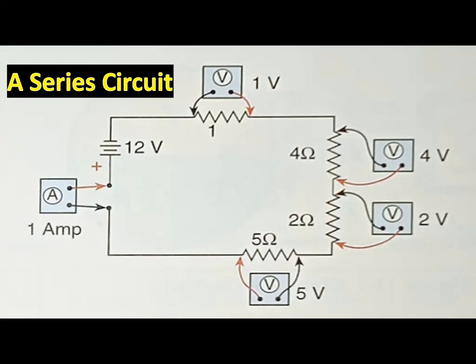The heater blower circuit is an example of a series circuit. The resistors in the blower circuit that control blower speed are switched in series with the blower motor. By adding resistance, the motor will slow down because it receives less voltage as the resistance is increased.